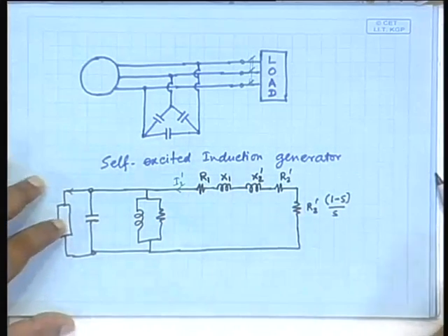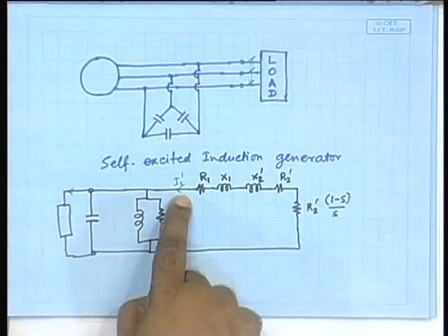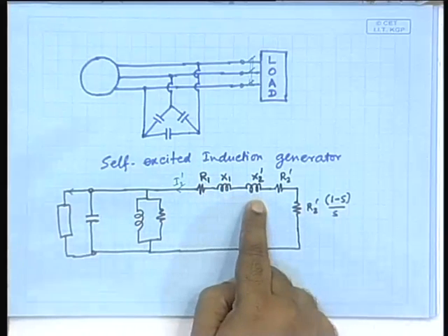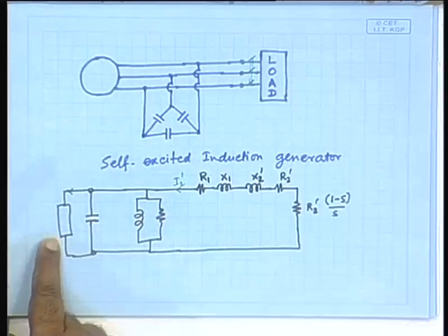That should be intuitively clear. The moment you have some current flowing here, the current has to be generated coming from here, and the current will produce reactive power consumption here. And it will become somewhat worse if the load is of the inductive type.